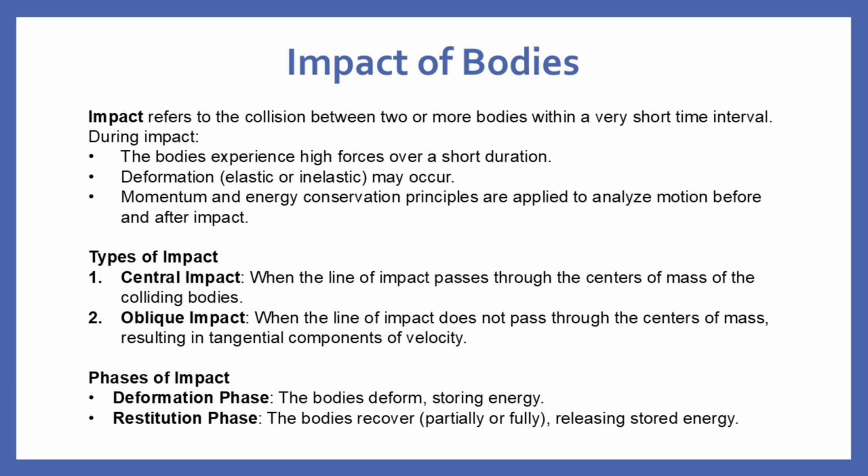Let's discuss the impact of bodies. When two or more bodies collide within a very short time, it's called an impact. During this event, high forces act over a short duration, causing possible deformation, which can be either elastic or inelastic. We use momentum and energy conservation principles to analyze motion before and after impact.